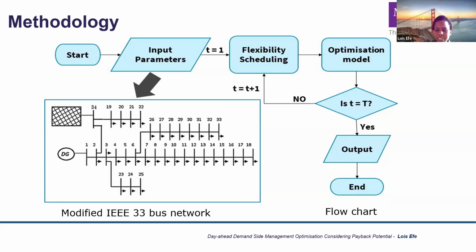So which optimization model was I dealing with? I was working with a nonlinear optimization model using a software called MATLAB, which was also embedded in MATPOWER. The objective is to minimize generation cost. And I also scheduled flexible loads as negative generators so that we're able to minimize costs within the generator, and the flexible loads are now acting as negative generators.